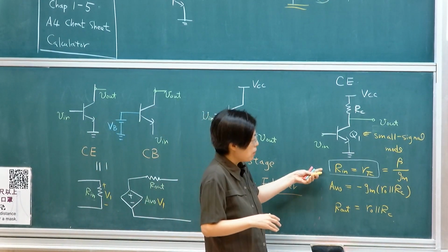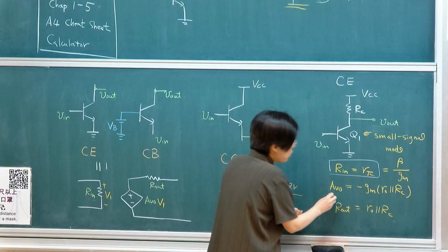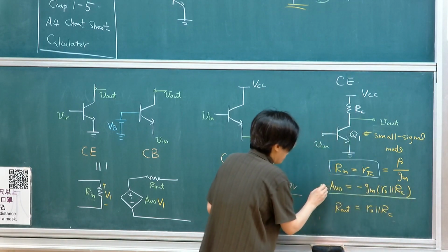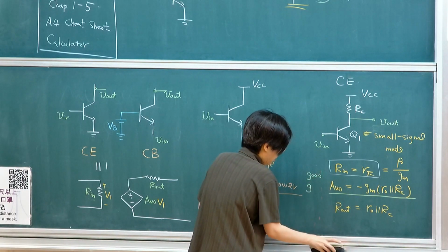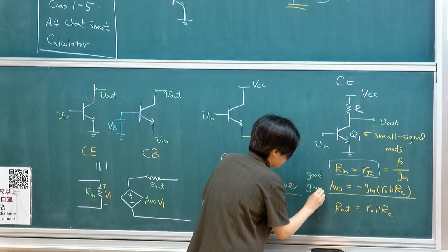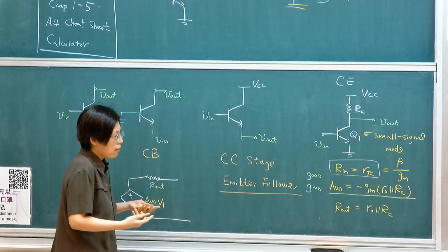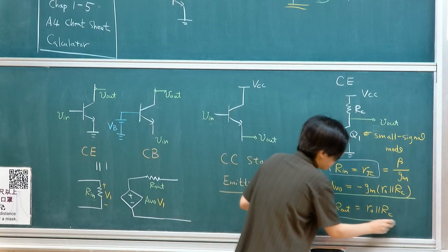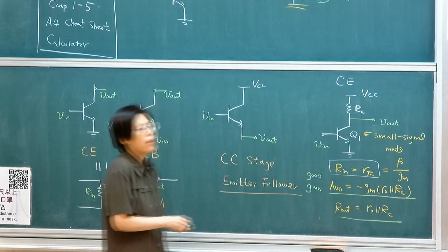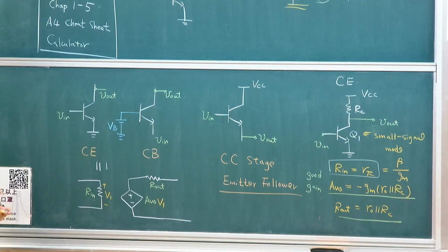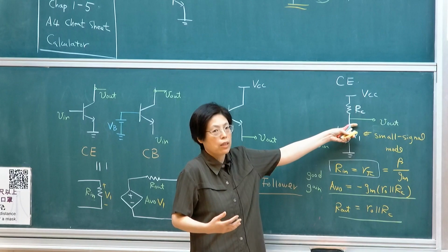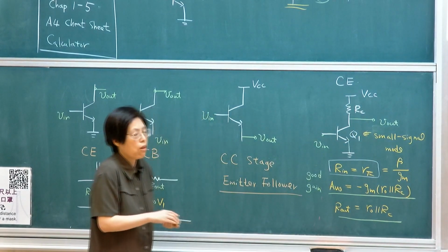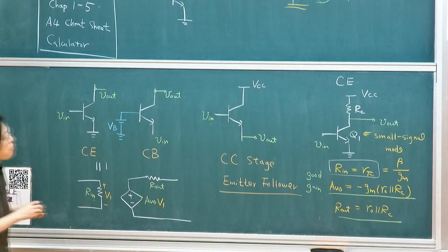So you have relatively high input resistance. We could establish relatively good gain. So this is providing a good voltage gain. But this is at the cost of relatively high output resistance. So input and output are both at a high resistance level. So that's not very ideal for voltage delivering, as I said. So typically, we need to add a buffer in order to deliver this if my loading is fairly large or loading current is fairly large.